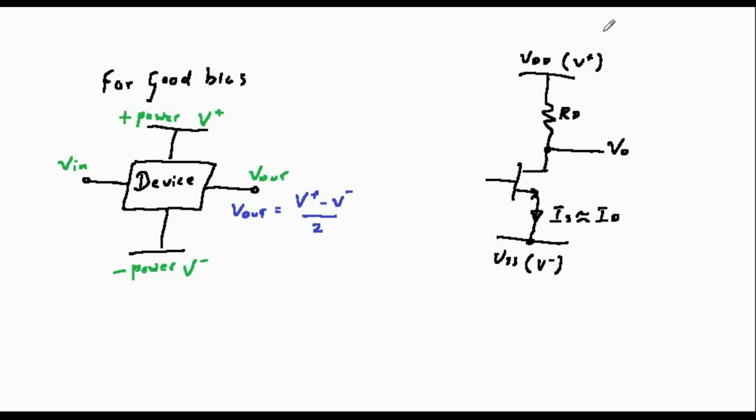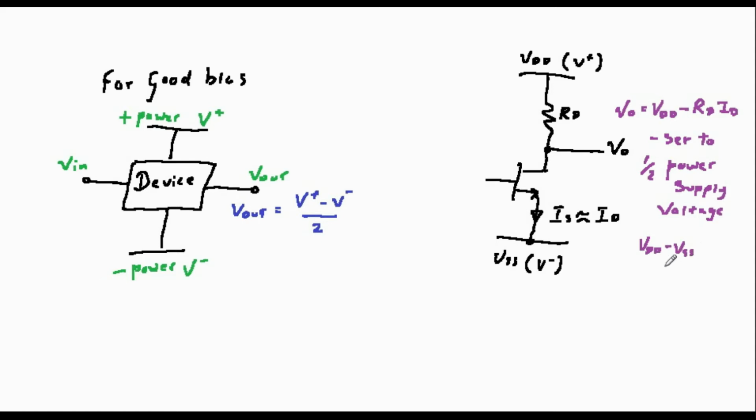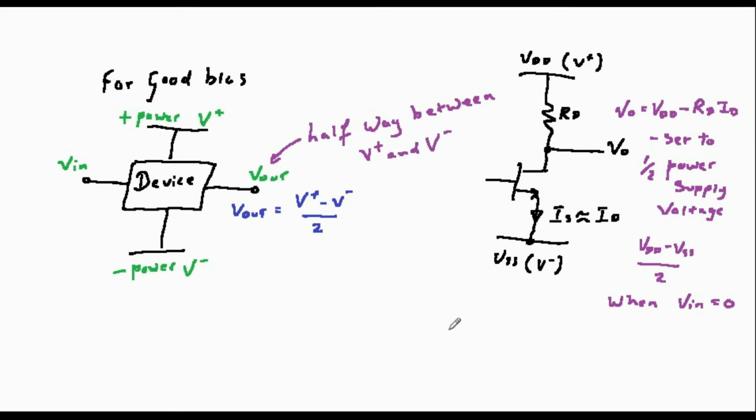With the ordinary transistor, or BJT, the strategy we adopted was to create a current flow through the device even when no input signal was present. This then enabled us to produce an output voltage at half the power supply voltage using a collector resistor. We can do exactly the same thing with an FET, but using a drain resistor.